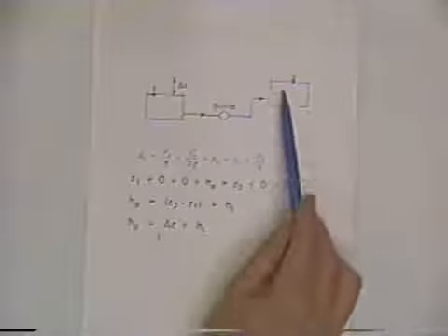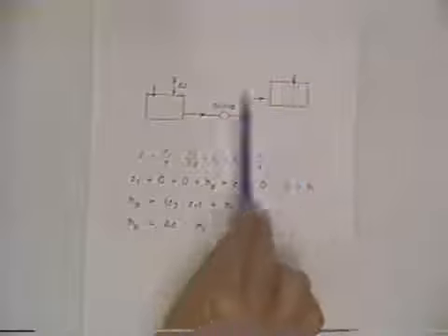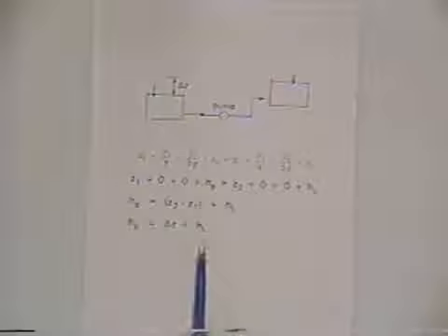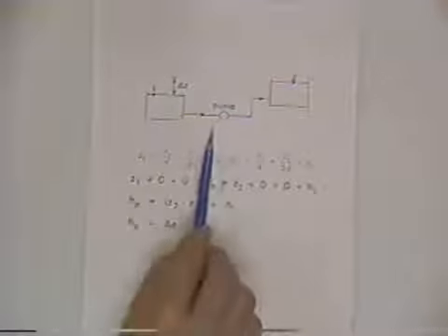Now the delta Z is a fixed number set by the physical configuration of the system. The head loss is a function of discharge. As we already talked about, head loss is some K times a discharge raised to a power. So this is a function of discharge, and the pump characteristic curve is a function of discharge. Head is a function of discharge. So we've got two head-discharge relationships, one characterizing head loss, one characterizing the capabilities of the pump.